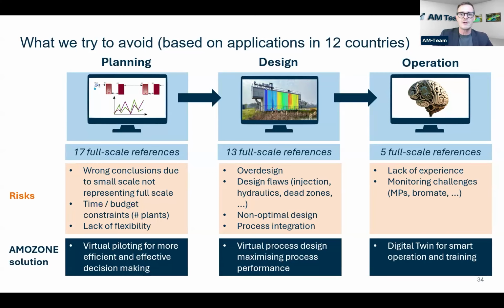And it really speeds up the whole training process. And of course, the monitoring is trickier. You cannot monitor bromate in real time. You cannot monitor the removal of the individual micropollutants in real time. And this is, of course, what AMOZONE offers as a soft sensor. So in that stage we are talking about smart operation and training.